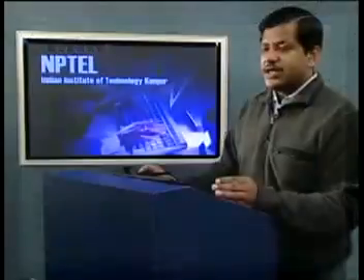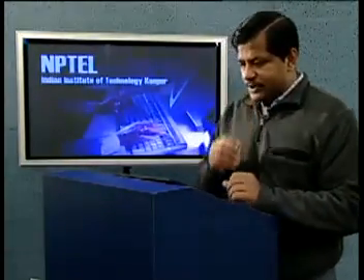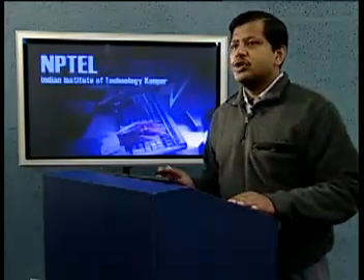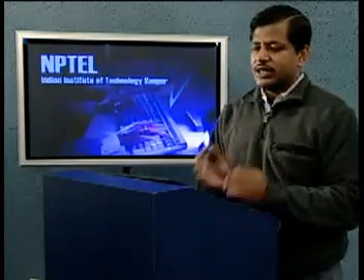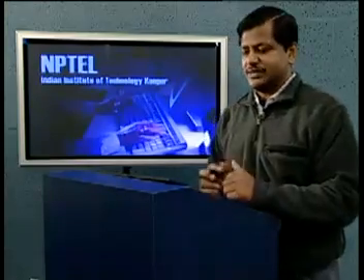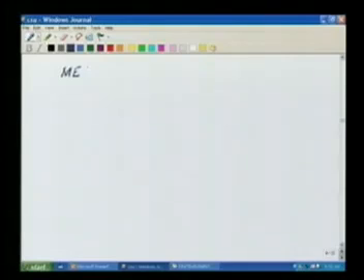So once we have the elements and the nodes, then the next step is to now define functions over these elements. By the way, the process of forming the elements and nodes is called meshing. So that process was meshing. That was the first part of any finite element analysis. So once I have made the mesh, then over these nodes I am going to define functions.